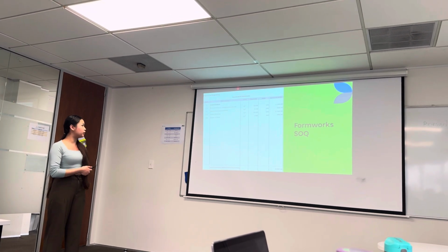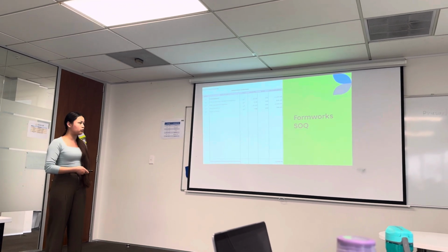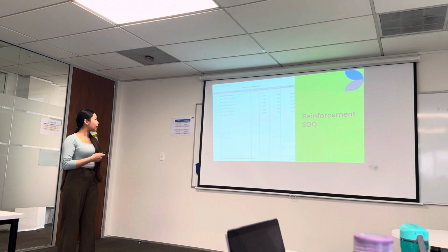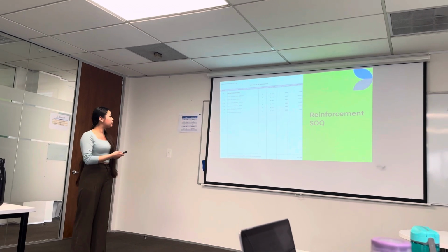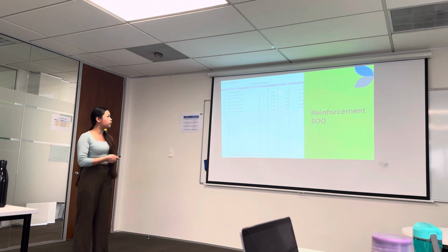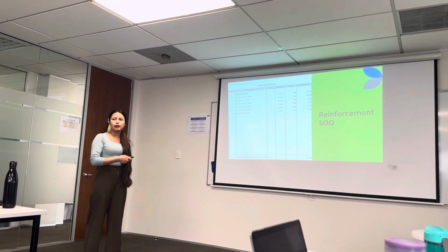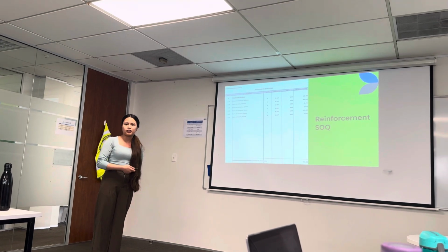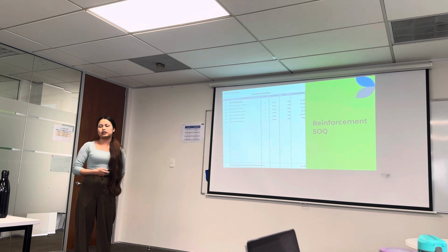Formworks, see, we always calculate the formworks in meter square. We have to mention it accurately. And the schedule of quantities for reinforcement, we calculate all of this in ton. First we get the diameter in mm, then we have to convert it into kg, and after that we have to convert it by dividing by 1000. It comes to the ton.